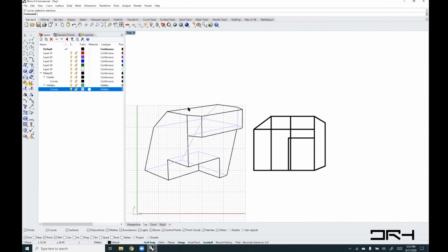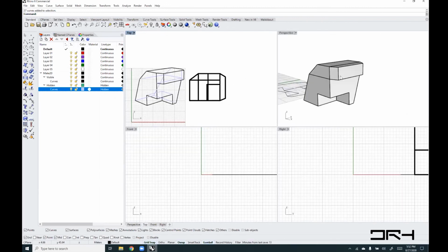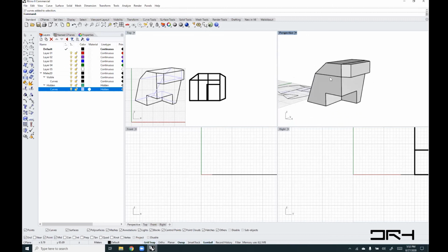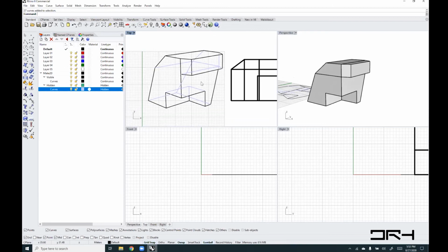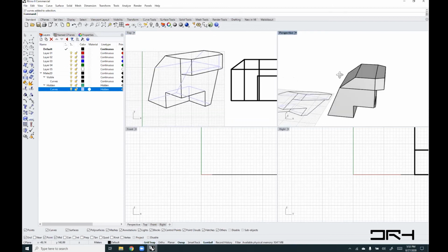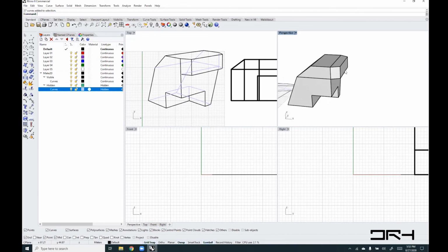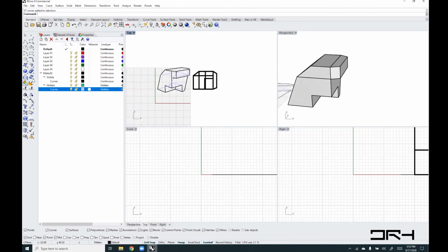So Make2D is really nice to use to extract what you see in this view as a flat drawing, and you can export it to any other program to do, for example, hatches or fillings, or Illustrator, or any other kind of program. If you want to extract, say, sections through this object, let me just hide the Make2D altogether.